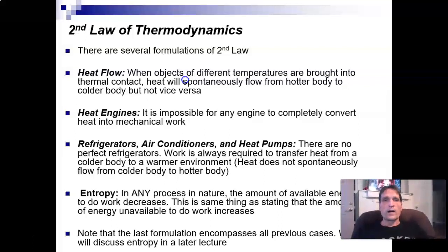Yet another way of expressing the second law of thermodynamics is that there's no spontaneous transfer of heat from cold to hot. So if we want to remove heat from a colder body, like a refrigerator, and kick it out into a warmer body, the room, it doesn't happen spontaneously. We need to apply work in order to move heat against the temperature gradient, in order to force it to go from cold to hot.